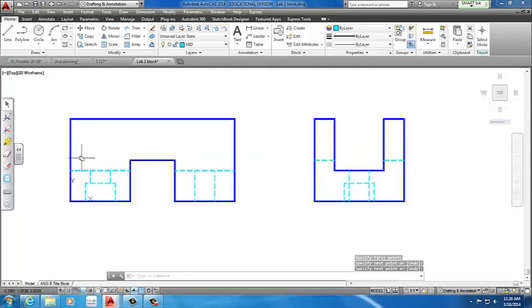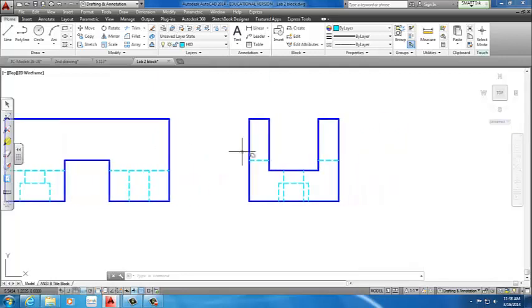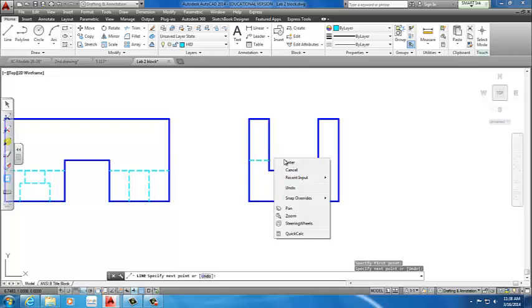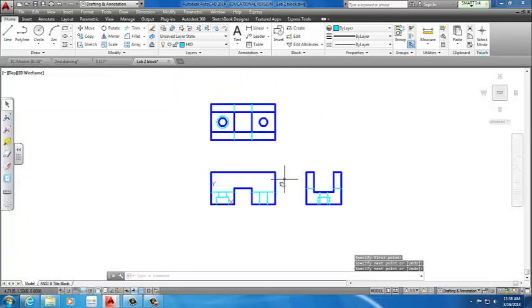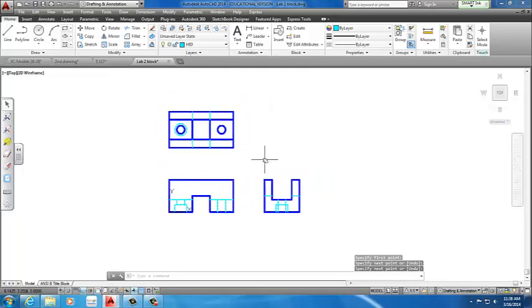This is the middle point of that 2-inch, because it's 1 inch back. You can play around to get what you prefer. What we could have done easily actually was just select the midpoint right there. There's a view cube, or you can go to view and play with these. Just draw a cross line from the outside, or you can hold Control and rotate it around until you select the right view. Inside is different, so make sure you have the right view from the outside. We put our title information in. That gives us all the hidden lines we need. Double click to change any things you like. At least I believe so.